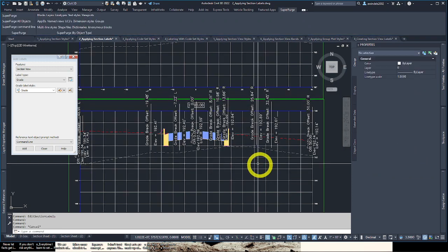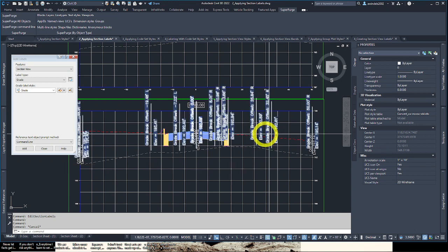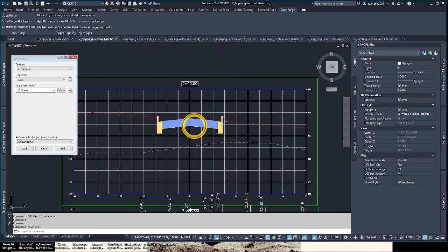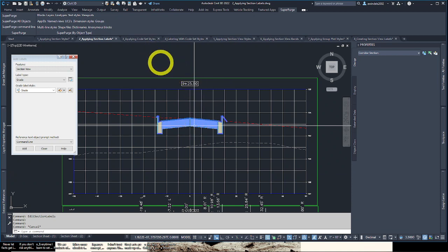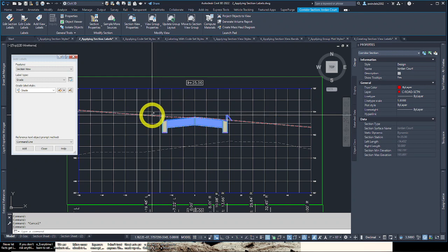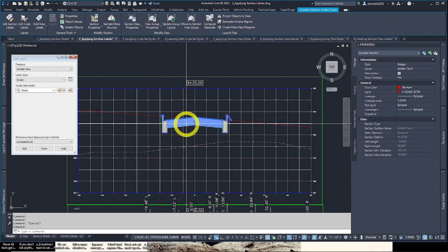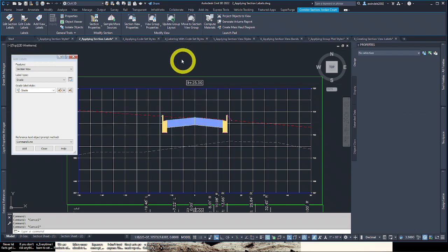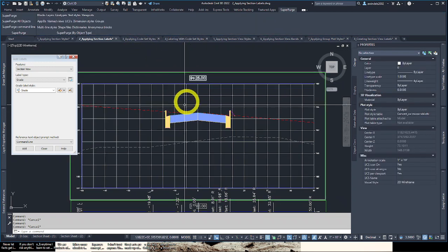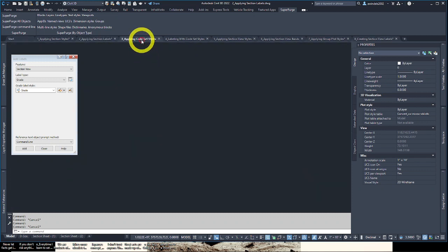So we're going to move on to page 213, and we're going to talk about CodeSet Styles. So CodeSet Style, it's a style and appearance of a corridor section. So this being your corridor section here, and while I'm talking about them, this is a regular section of just a surface of a straight line cut right through it, perpendicular to the alignment. This is the cut through the corridor and its assemblies within. I'm going to go further by going to this while I'm talking about them.